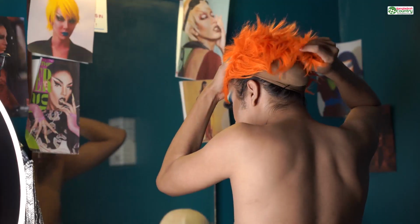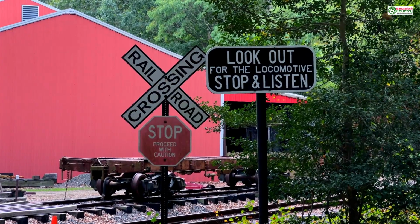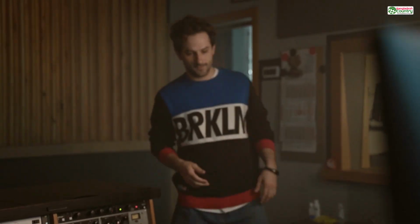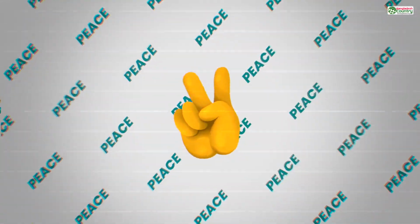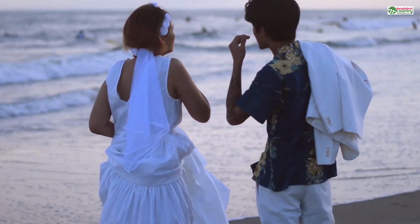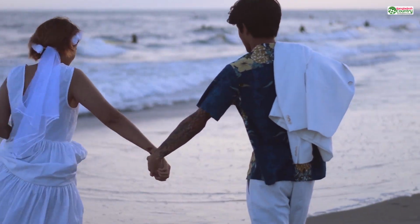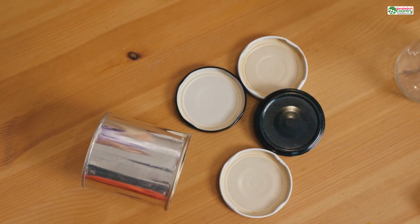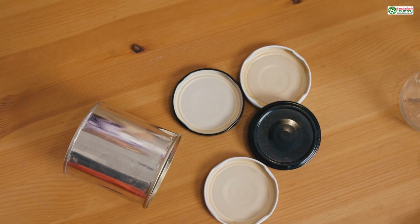But then just as you're about to add it to your cart, you see a new error message pop up. It's a single terrifying technical-sounding word. Warning: your model is not manifold. What on earth does that mean? It sounds like a problem with the Starship's engine, not a 3D file. This error means your model has holes. It isn't watertight. And just like you can't fill a leaky bucket with water, a 3D printer can't fill a leaky model with plastic. Sealing these digital holes and making your model perfectly solid is the next, and perhaps most critical skill you need to master. And that is exactly where we're headed.